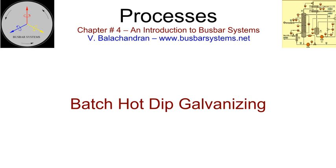The galvanizing bath is maintained at a certain controlled temperature. It is, therefore, necessary to preheat the job before galvanizing. Preheating will depend upon the profile and cross-section of the job. For some of the small members, galvanization can be carried out without preheating.